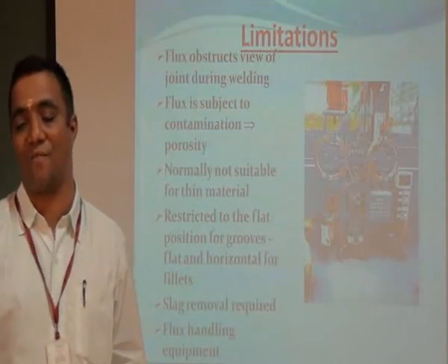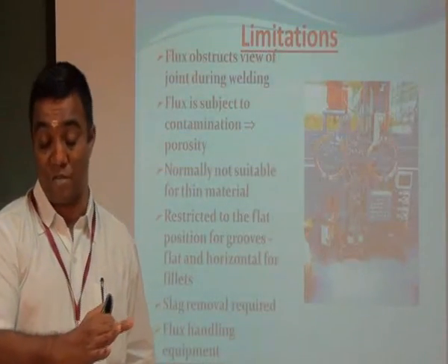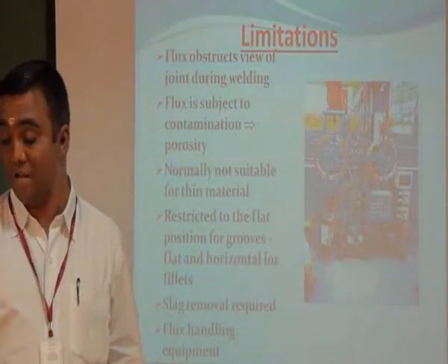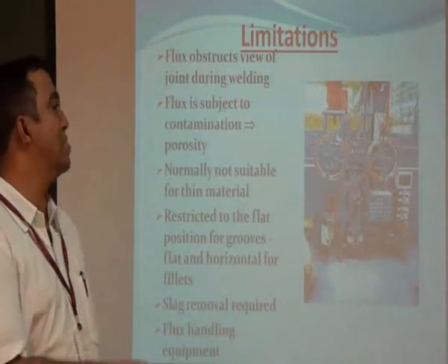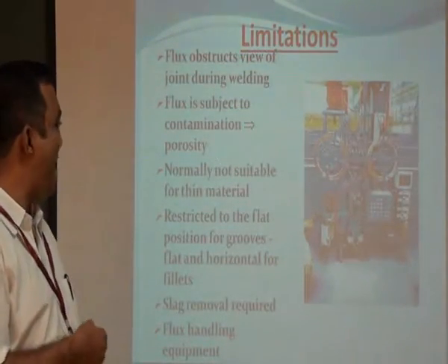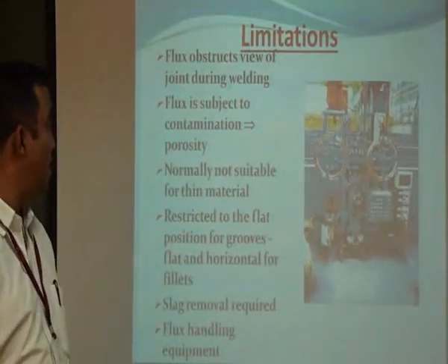Remember that not all fluxes can be reused. Only the flux in the topmost layer can be reused for this submerged arc welding process again, and if you use contaminated flux, it results in porosity.